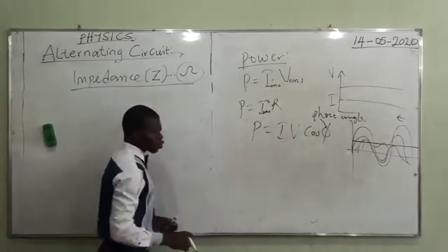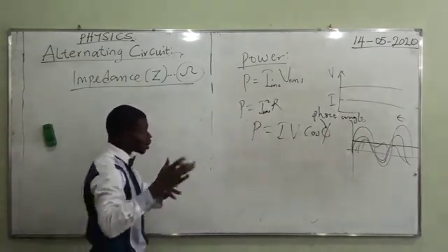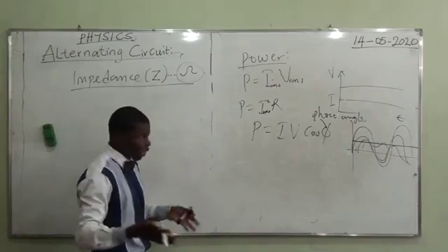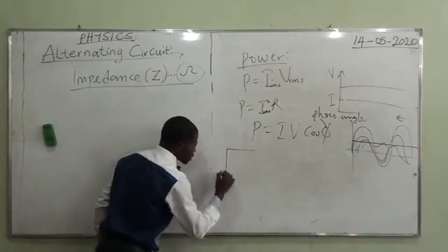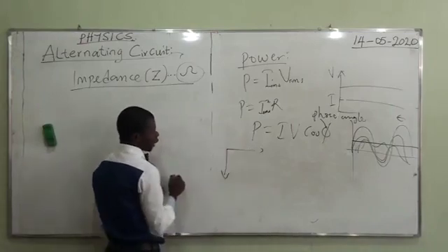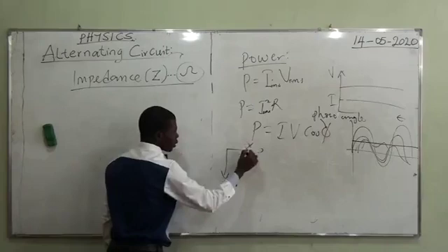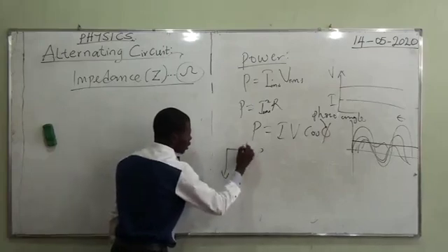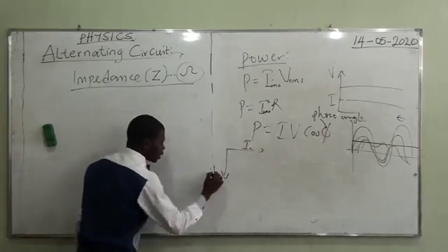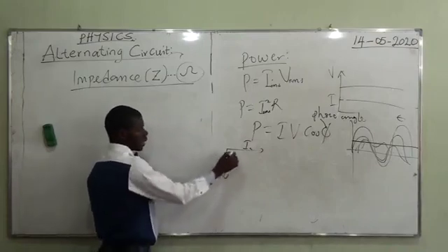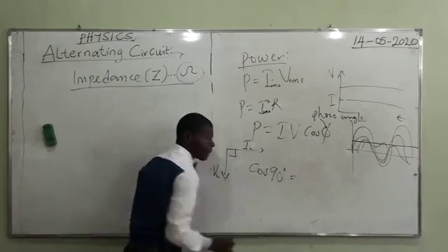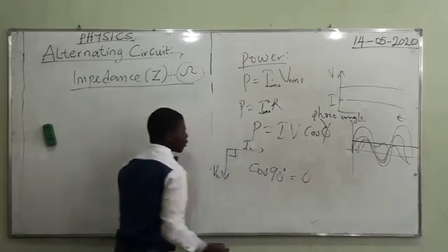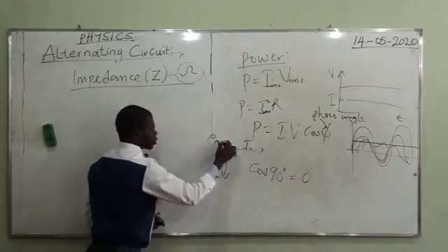So, back to business. I want to show you how power is not lost or dissipated in a capacitor circuit or inductive circuit. You have this phase diagram or vector diagram. The current is here for the capacitor now, and the voltage is here. And I told you the current is leading by 90 degrees. So, can you help me and take the value of cos 90? You will get 0. This is for capacitive circuits.